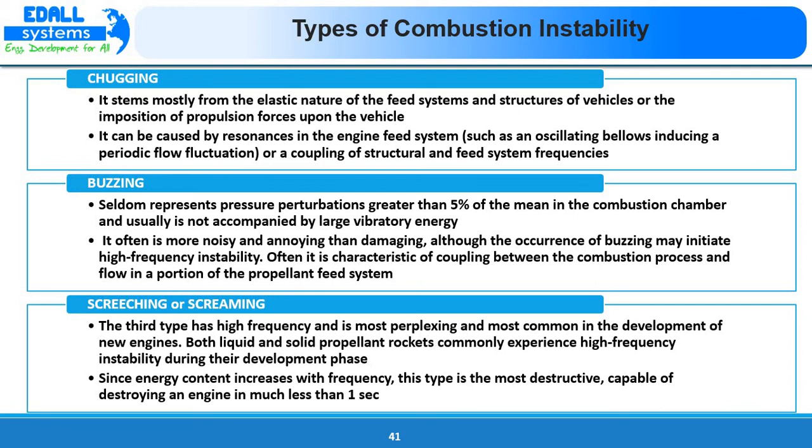The next one, that is buzzing, seldom represents pressure perturbations greater than 5% of the mean in the combustion chamber and usually is not accompanied by large vibratory energy. It often is more noisy and annoying than damaging, although the occurrence of buzzing may initiate high pressure instability. Often it is characteristic of coupling between the combustion process and flow in the portion of propellant feed systems.